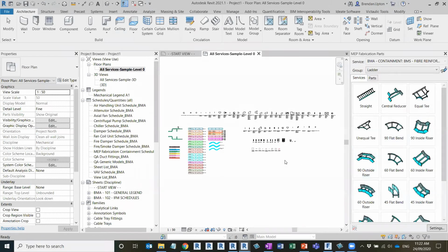So the next thing, and coming back to the core question that I know was being asked, how do you load custom databases? That's pretty much how you would do it. You make sure it's cleaned out first, and then you load your custom one into your fabrication product, and then you load that into Revit through this window.